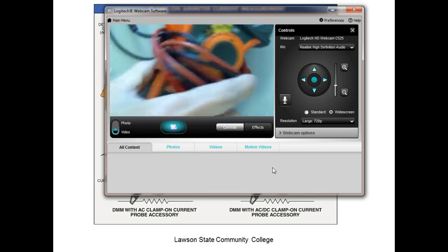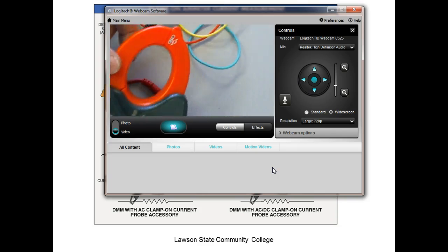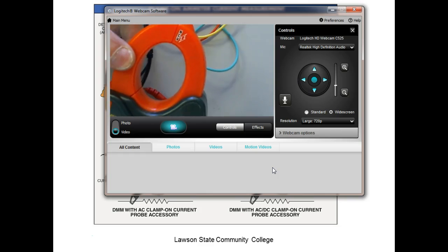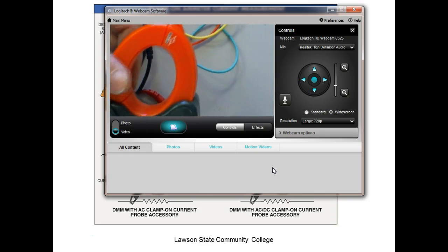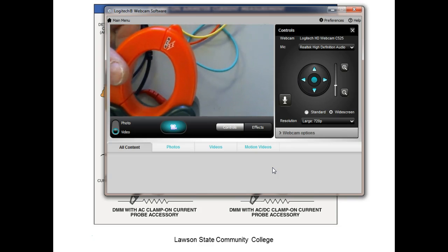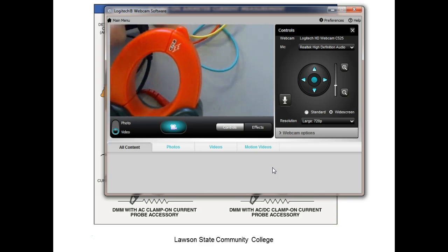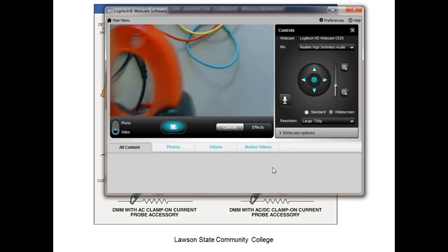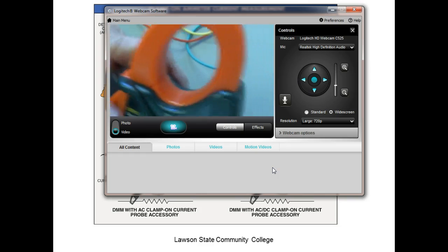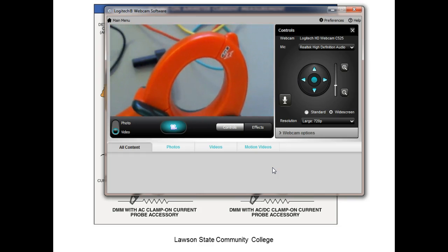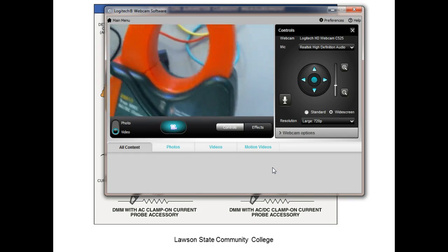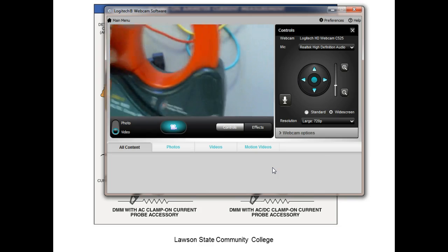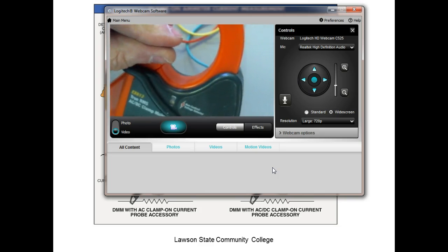The number of windings. So if you got enough slack on these guys, by the way, you can loop. So if you come over here and loop it twice, then your meter's going to measure twice what's there. If you loop it 3 times, your meter will measure 3 times what's there. So all you have to do is a little math, and you can make these guys measure a lower current. If you got enough slack in your wire, just by doing what? Looping the wire. That's a trick I learned a long time ago from a friend of mine. I said, man, we can't measure that. He said, well, just loop the wire, Rich. And every time you loop it, if you got enough slack, you're adding more coils to the wire. The magnetic fields combine, and your meter can measure lower current.